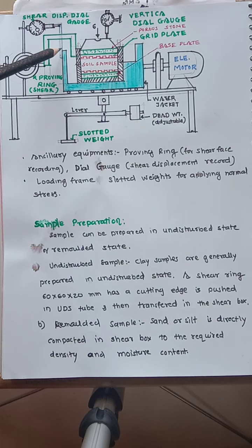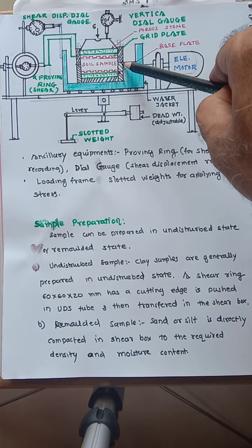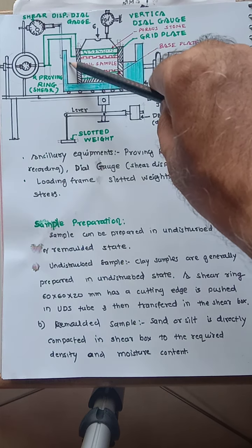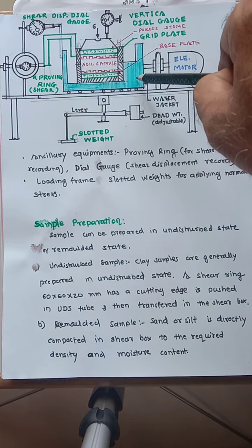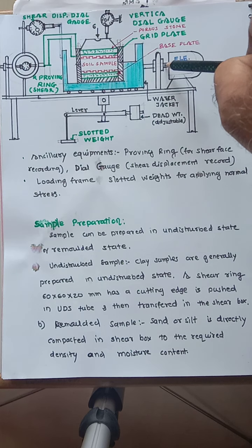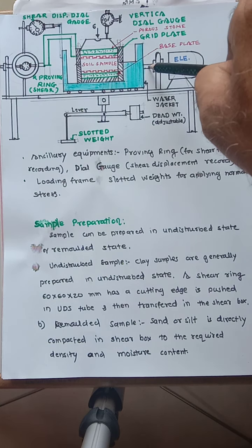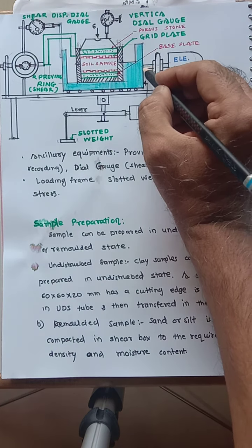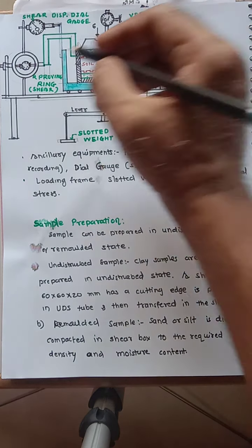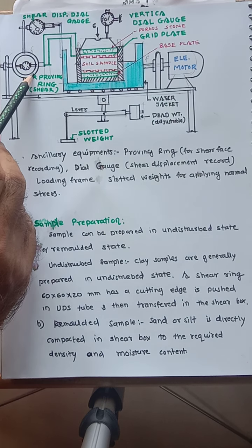This is a plate attached to this box. Okay, this outer box, you can see it has a slot here, a solid slot, and this one. This is the outer box, or called a water jacket. Okay, and this is the plunger. Force is applied by this motor. Okay, so this motor applies a constant rate of shear force. Okay, so this applies here the F, which is measured here. Okay, so shear force is measured in the proving ring.